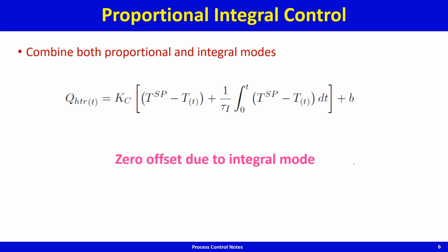If somebody opens up a window, or maybe somebody is entering from outside and the cold air from outside gushes in, the temperature of the room will suddenly drop. Initially the temperature of the room is at set point, but then it drops down very sharply because cold air rushed in. Now as it starts to drop sharply, the error is small. This is T set point and this is T, therefore T set point minus T is a small number. The integral of this will also be a small number.